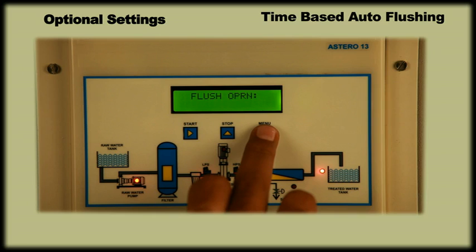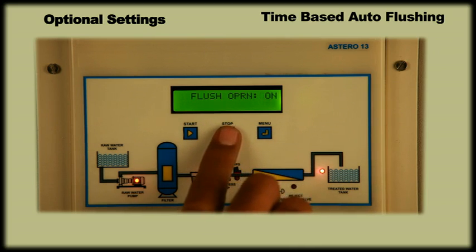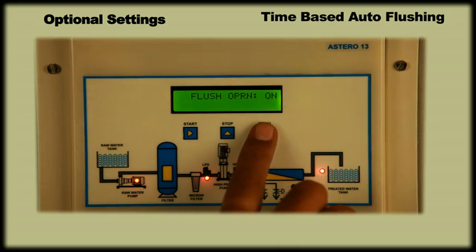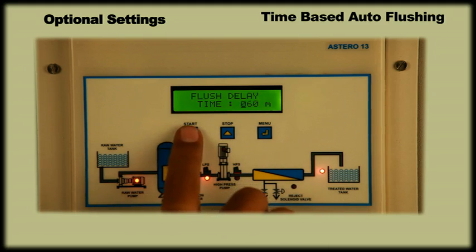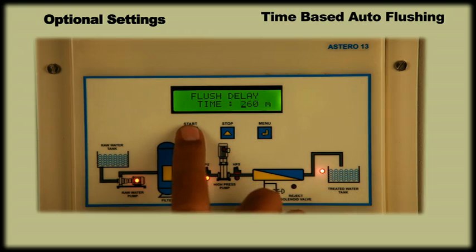On pressing Menu key, it will show flush operation off by default. Using the Stop key, you can turn it on and press Menu key. The display will show flush delay. On pressing Menu key again, it will show previously set delay time. This is the duration of time after which the panel will automatically start flushing. You can set the time in minutes. For your understanding, let's enter 240 minutes and press Menu key.